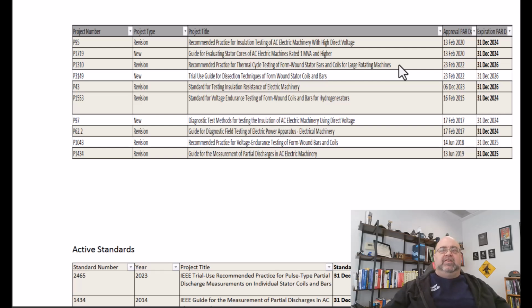In the end, the drives actually met 519 in total demand distortion, which is the current part, which is a relationship of the amount of current to the short circuit current of the branch. And 519 unfortunately states that it doesn't affect anything else, it just goes straight back to the transformer, which we know is false. That's not correct information.